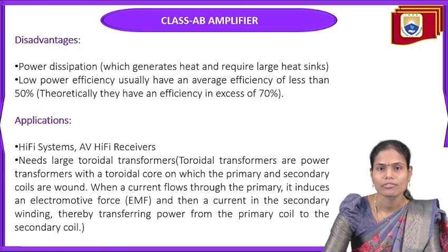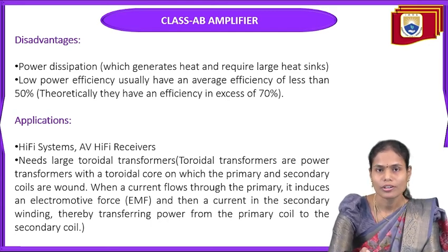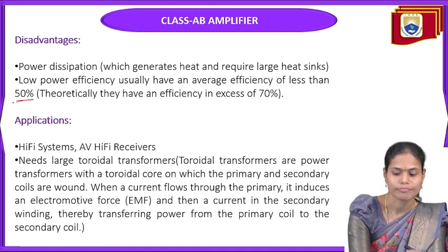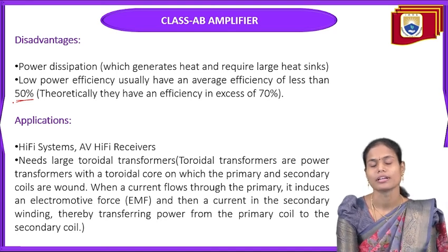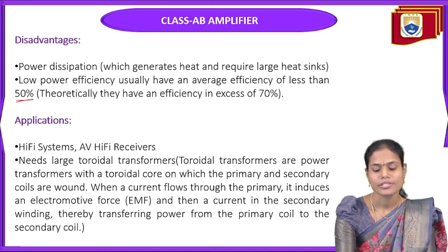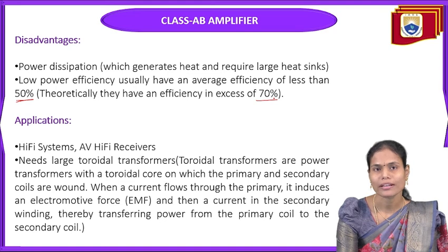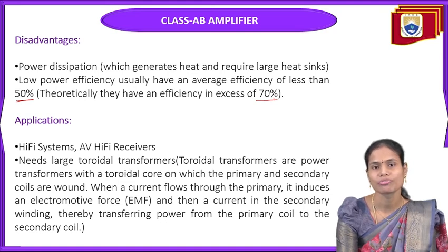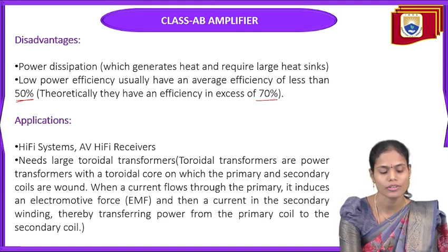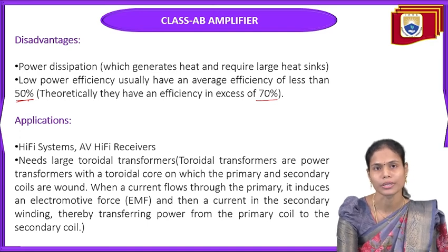While coming to the disadvantages, we have much power dissipation here. So in order to reduce this, we have to utilize heat sinks in the circuit, and efficiency is less than 50%. Theoretically, we estimated it as 70%, but in the practical case, we can reach only up to the 50 to 60 range. So that's why I mentioned it as 50% only.